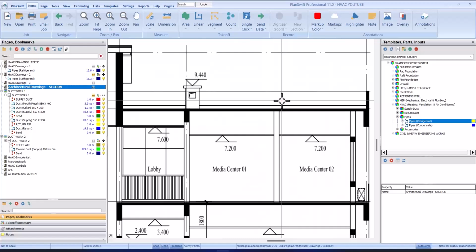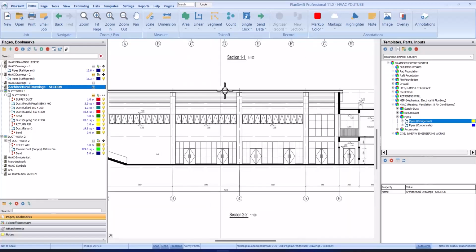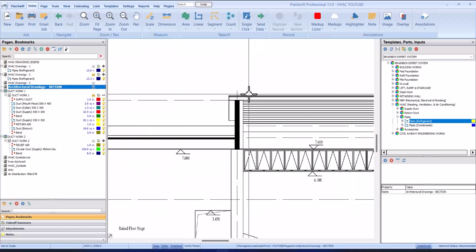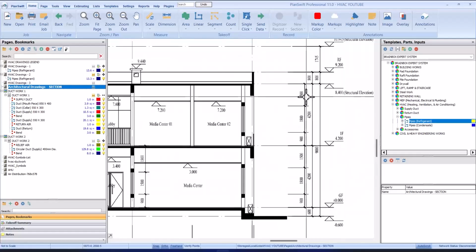Since this is outdoor here, 800. So our rise now is going to be 1.5 meters from this point up to this point. 1.5 meters, or we can make it 1.6 depending on the allowance you want to allow for it.